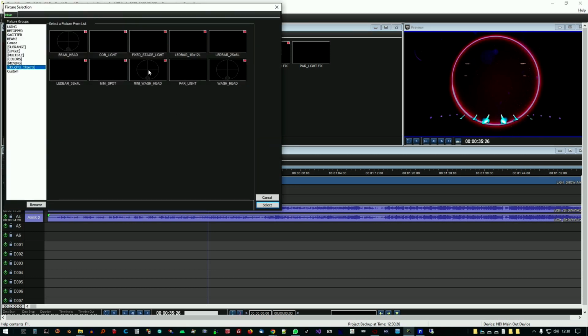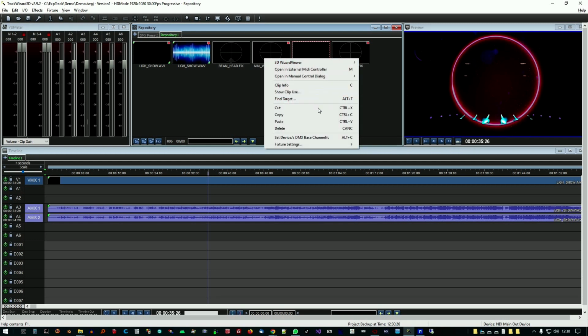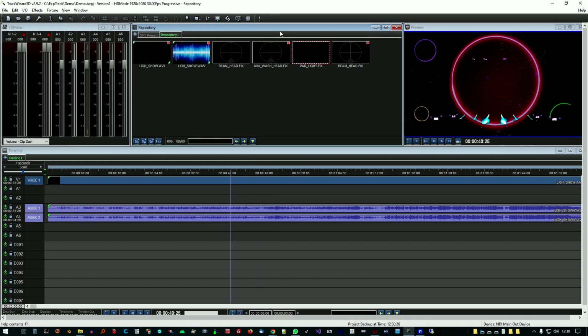Each DMX fixture is identified in the system and on the timeline by fixture type and DMX base channel. We can have several fixtures of the same type that have different base channels. To add 2 fixtures of the same type we can duplicate the same object and assign a different base DMX channel, which we will add on the timeline at the points where necessary. Let's start our lighting project by adding fixed fixtures to create ambient light that is evenly distributed throughout the scene. We insert on the timeline 4 fixed lights with base addresses 10, 30, 50, 70.